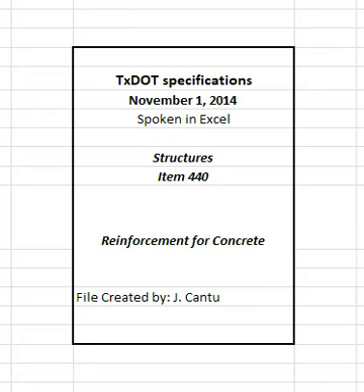Provide bars conforming to ASTM A615, ASTM A996, type A, or ASTM A675, grade 80, meeting dimensional requirements of ASTM A615. 2.5 Weldable reinforcing steel. Provide reinforcing steel conforming to ASTM A706 or with a maximum carbon equivalent, CE, of 0.55% if welding of reinforcing steel is required or desired. Provide a report showing the percentages of elements necessary to establish CE for reinforcing steel that does not meet ASTM A706, in order to be structurally welded.